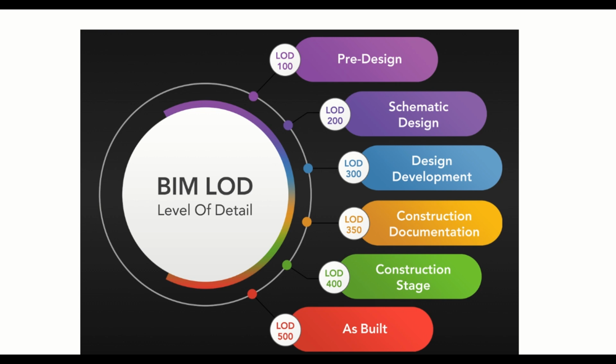At this stage, the dimensions and shapes of the services or the equipment are approximate, or I would say accurate, at LOD 300. It means if the pipe diameter they have mentioned is 100 mm, it will be 100 mm later on as well. If it's changing, that's a different thing. We all know that in BIM, sometimes there are changes, but the actual terminology of LOD 300 means they have defined this particular diameter as 100 mm, and it will be 100 mm if there is no major change at later stages.